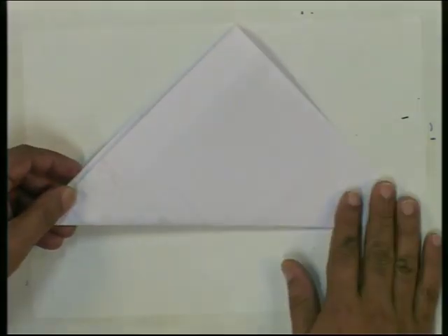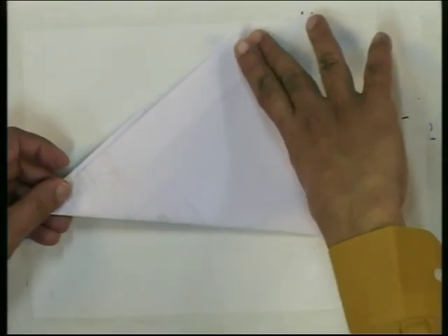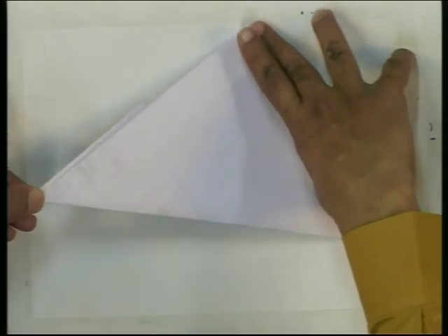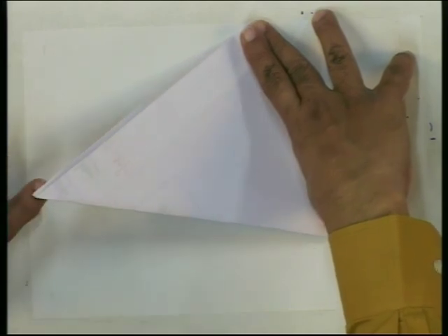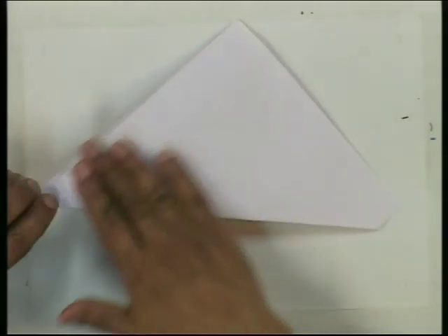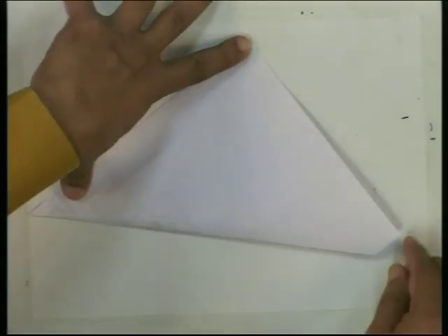What is your shape function 1? Keeping the others 0, this should have unit value. What is the shape of this? It is the equation of the plane of this inclined plane. This is unity, so a triangular plane will simply remain a plane. The equation of this inclined plane is the shape function. What is the shape function of node 2?